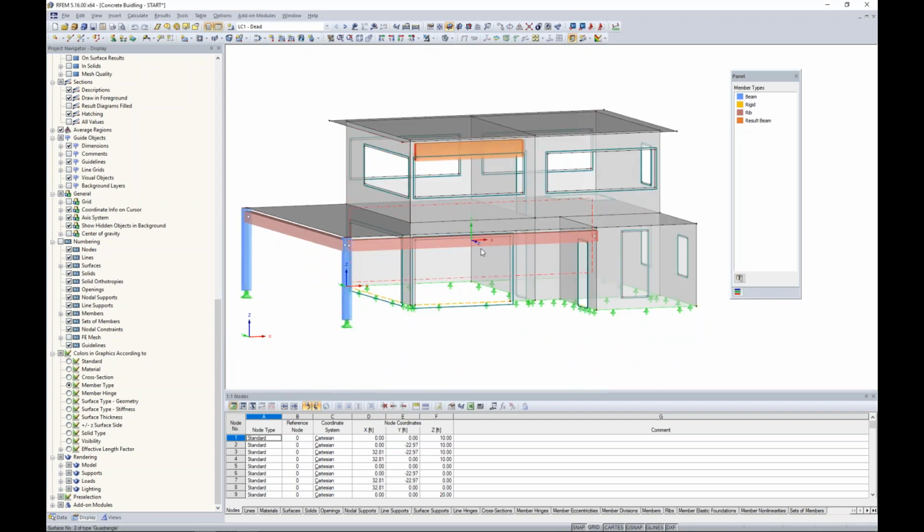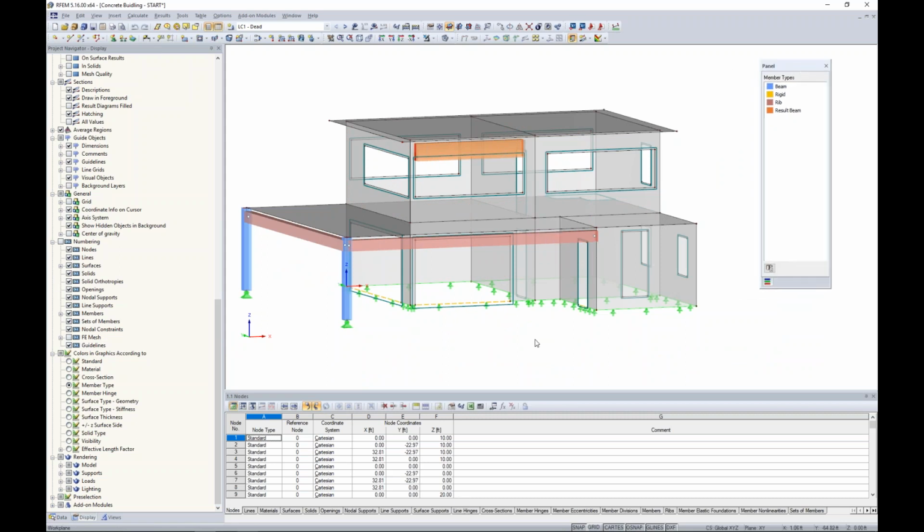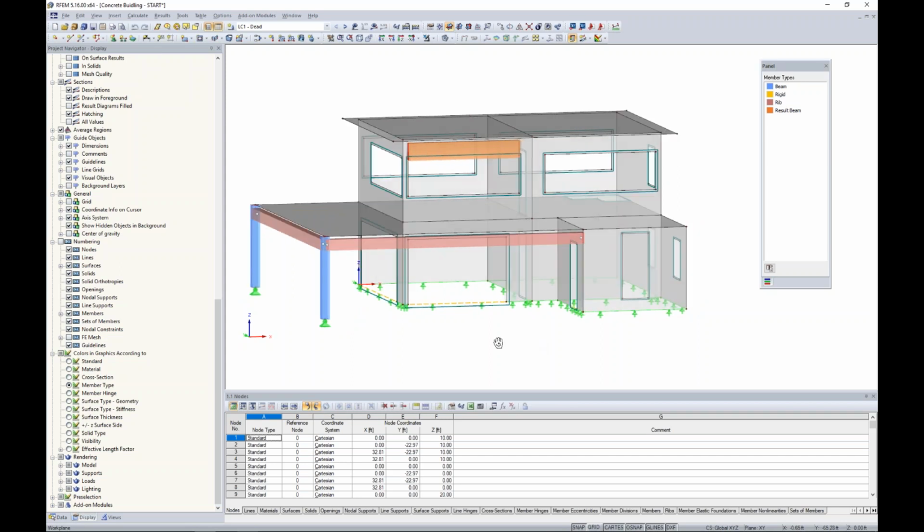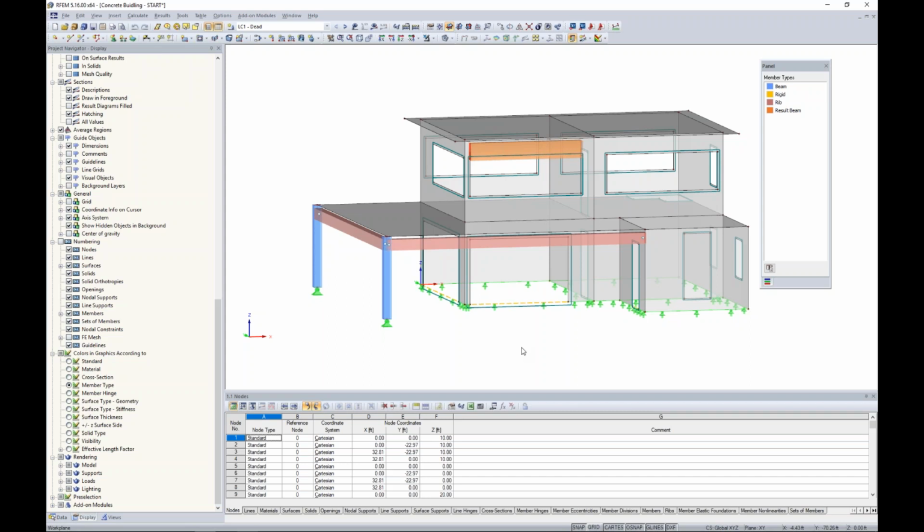Okay, so now that we have covered the basics of the surface and beam members, I want to talk about the I cracked. Now the I cracked is just simply the gross moment of inertia multiplied by a factor, and this comes directly from Table 6.6.3.1.1(a) within the ACI. The ACI requires us to take into consideration cracked section properties. Now this factor multiplied by the gross moment of inertia varies for each element, whether it's a column or a beam or a surface. So by default, the program will automatically use the gross moment of inertia.